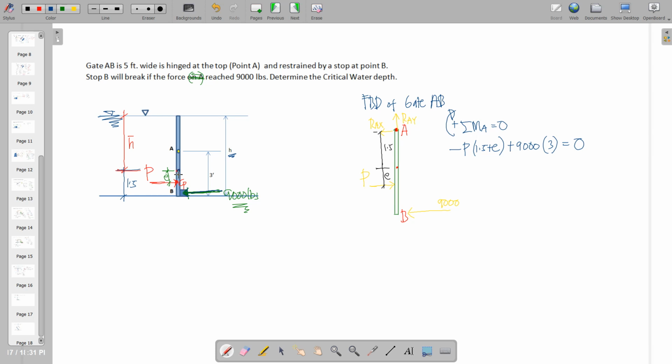To the center of gravity, and the center of gravity is half of the dimension of the bottom of this, which is 1.5. So therefore, from the liquid surface, we have H up to the bottom. So therefore, H bar plus 1.5 is equal to H. So hence, we can write that H is equal to H bar plus 1.5. So we express H bar in terms of H: H bar is equal to H less 1.5.